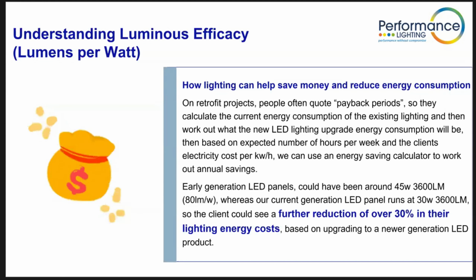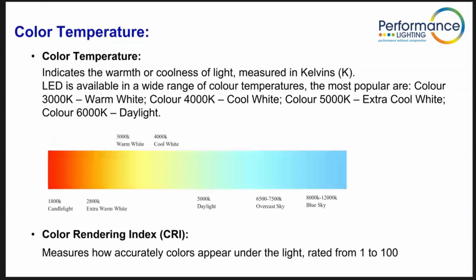I think people sometimes think, oh, we've got LED, so we don't need to upgrade. But it depends how old that LED is. So as you can see, there's lots and lots of potential in energy saving, but it is really important to think about the lumen output rather than just what wattage you want to buy. The other thing to think about when we talk about LED and fluorescent, but certainly more so in LED, is the colour temperature.